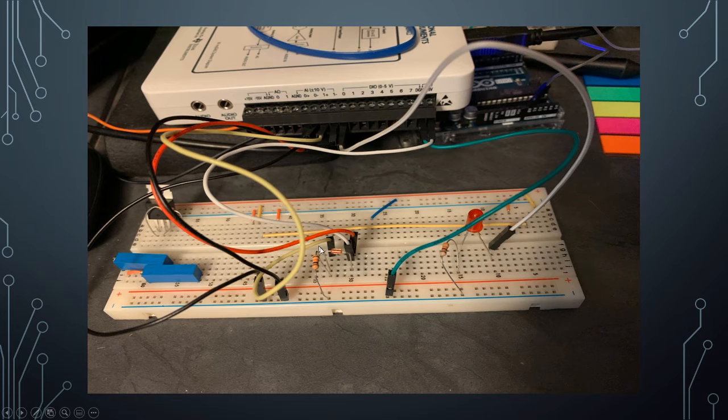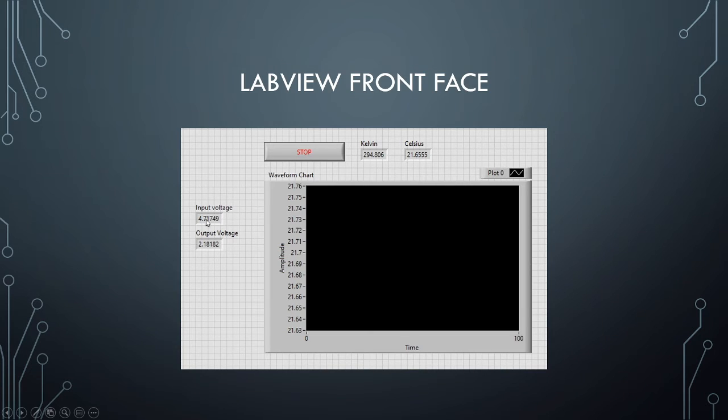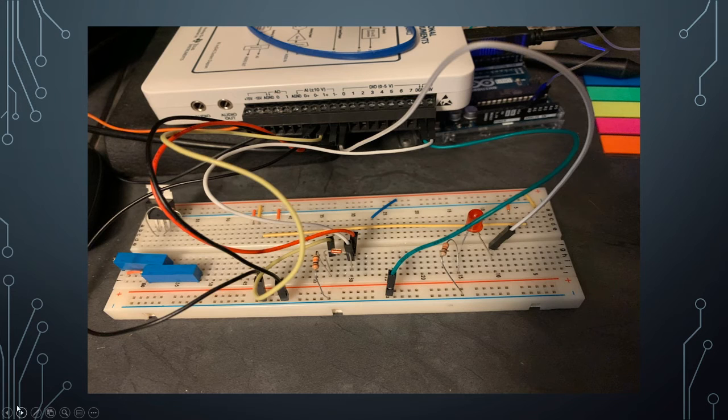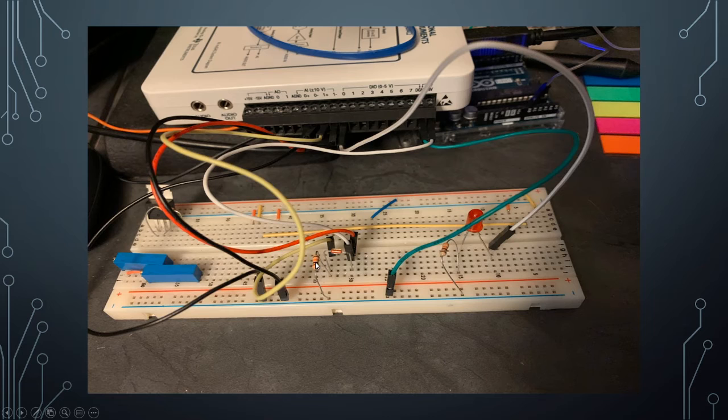All right, here's the physical circuit. You can see the thermistor here is connected to 5-volt input. So it's always getting 5 volts. Well, roughly, as we see here, about 4.7. But that's why we needed to know the input and not just give it 5 volts, because then it gives a little more accuracy. And the 10K resistor here is connected to ground.